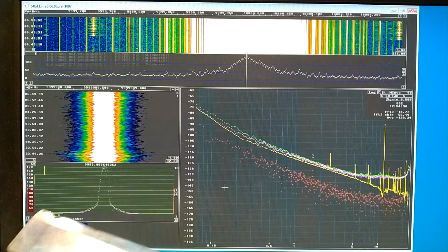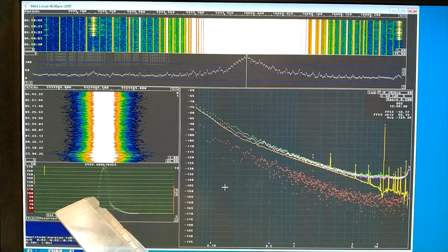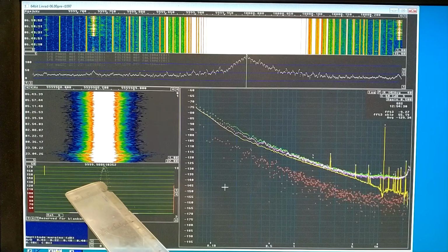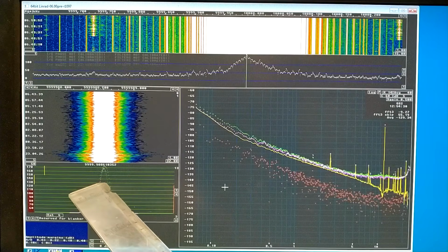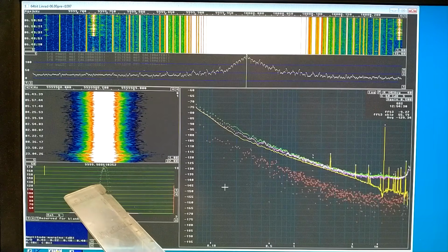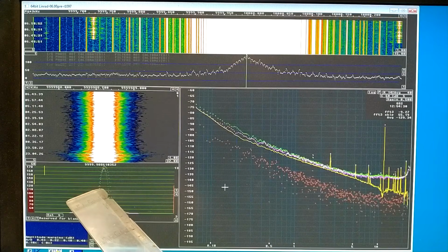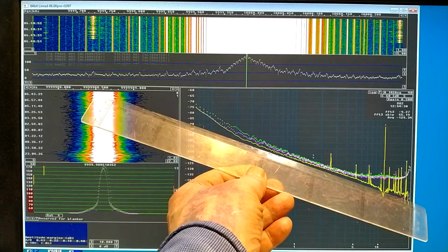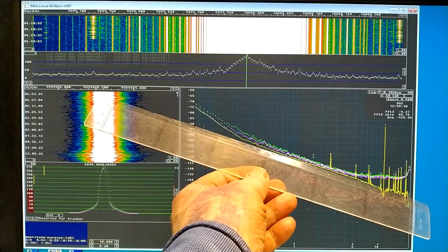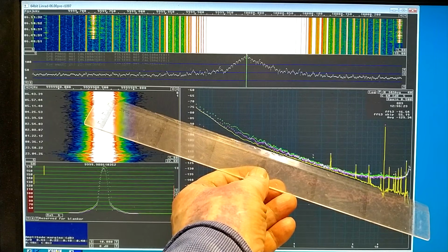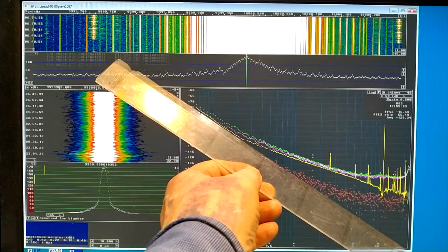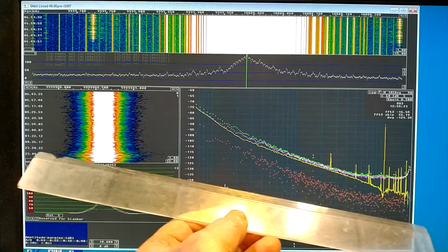Now, for this procedure to work, as I have written the code, I have the same filter for both channels, so the signal must be very close to each other, nearly the same frequency. To achieve that, they are phase-locked to a reference, a frequency-shifted rubidium source. And that phase locking could introduce noise from the rubidium source that would be correlated in the two channels. And that could have something to do with this, which I will check later.